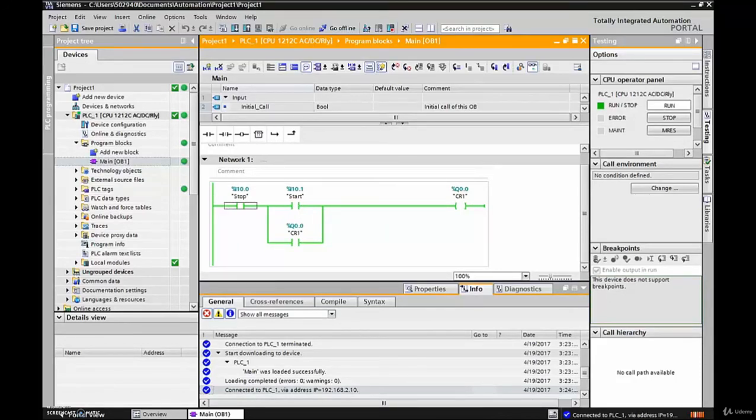Now I'm going to open up my start push button, but I should have another path of logic down here. Oh, very cool. So my output is still fired on my PLC here. And now I'll hit the stop switch, and that should kick out everything. Very cool. Okay, so the stop push button is now closed. Start push button is closed, energizing my control relay, turning my output on. I will now let go of my start push button, and then in order to interrupt this, I'll just open up my stop push button. There we go, and that turns off my control relay.